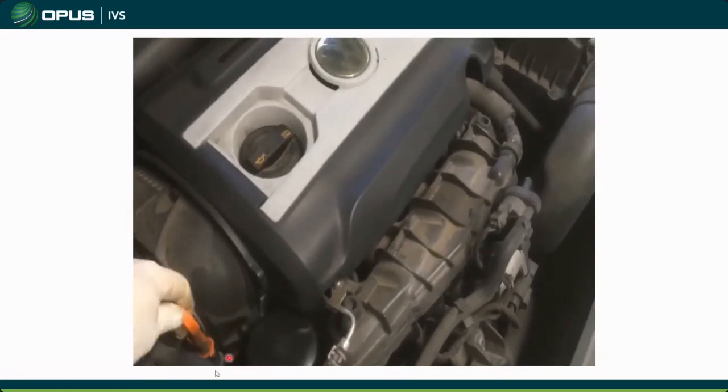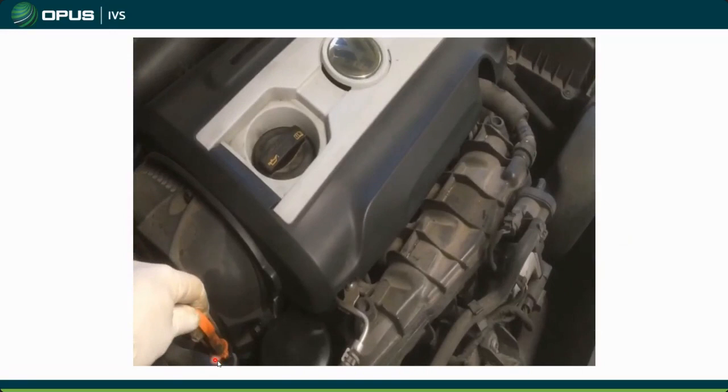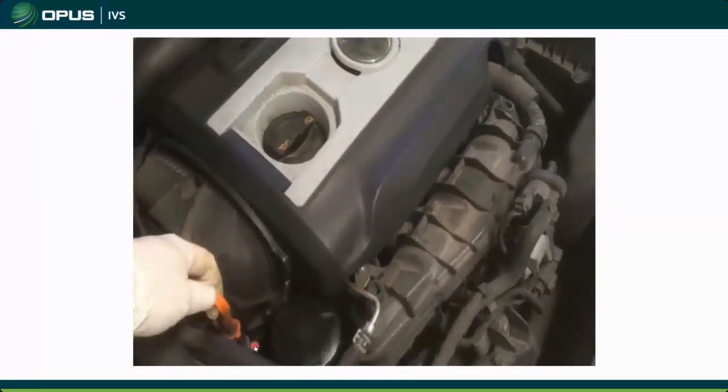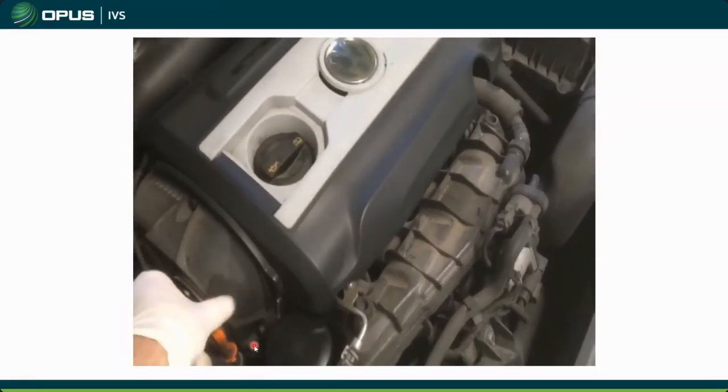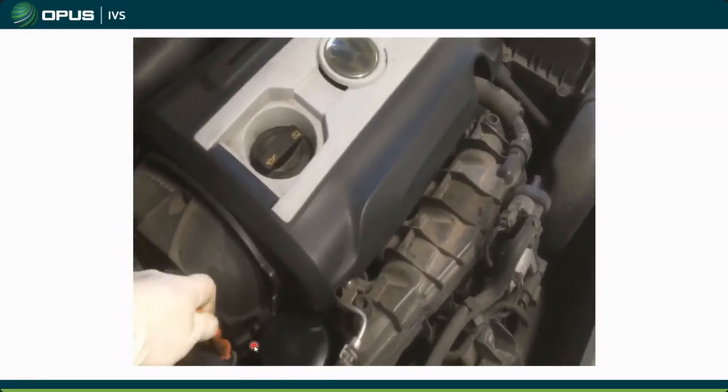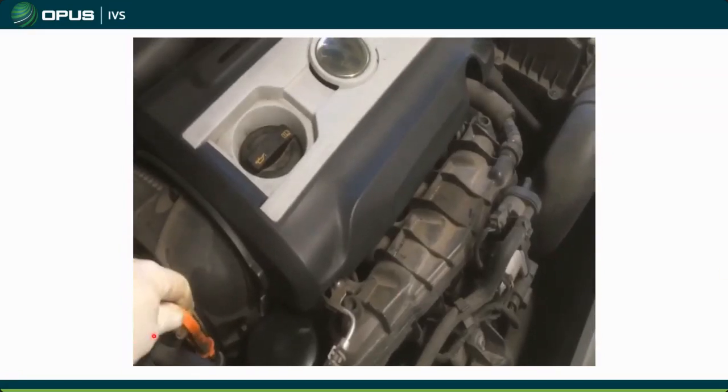So as soon as he pulls the dipstick tube, you now don't have enough vacuum in there for the valve, the diaphragm, to make that noise. So that's kind of the noise you'll hear, that real high-pitched squealing. Let me turn that off because it's annoying.